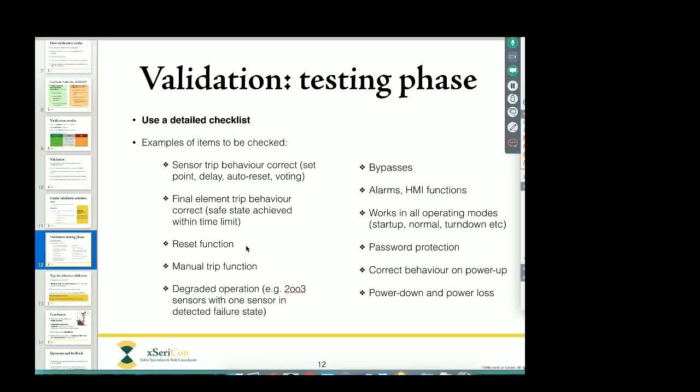Every safety function will have some kind of reset function, so check, does the reset function work? Does it do the correct thing? Manual trip. Manual trip is optional, but if you do have, let's say, a hand switch to trip a safety function manually, does it work?